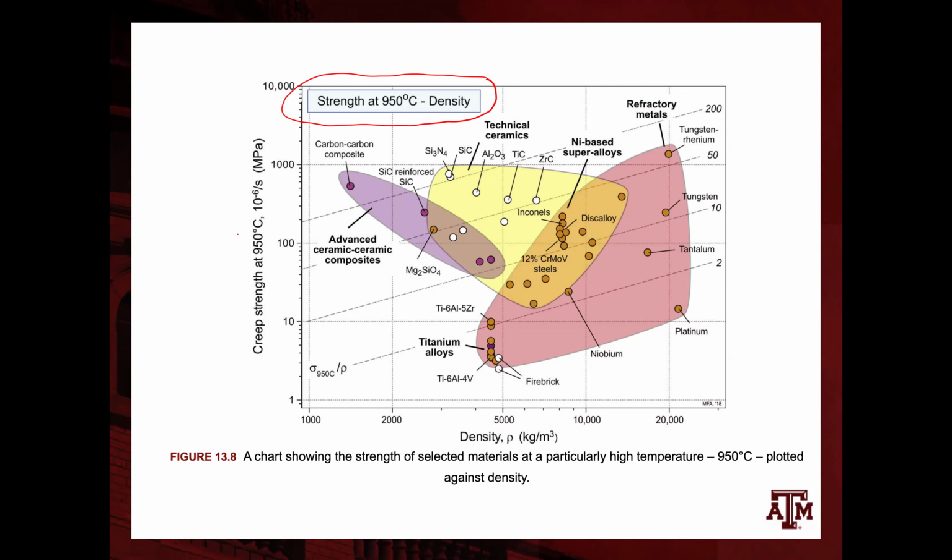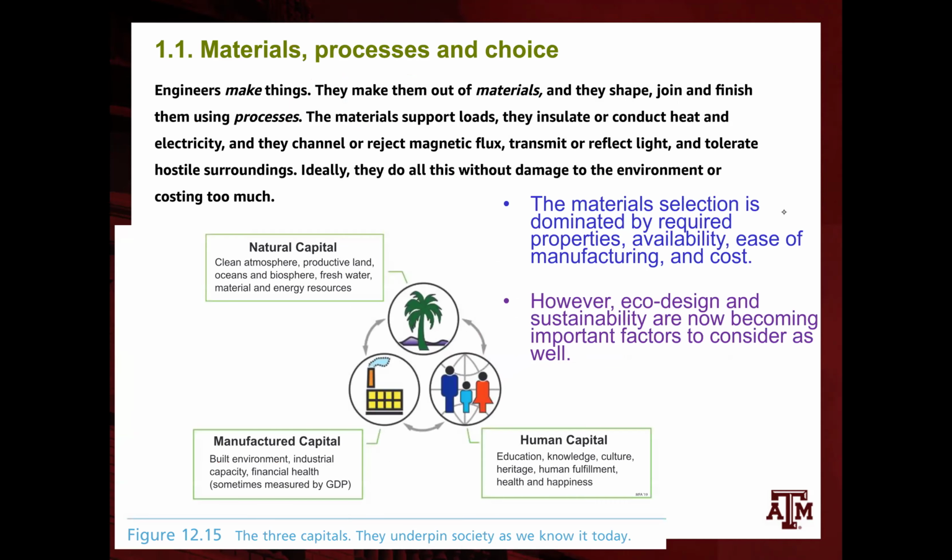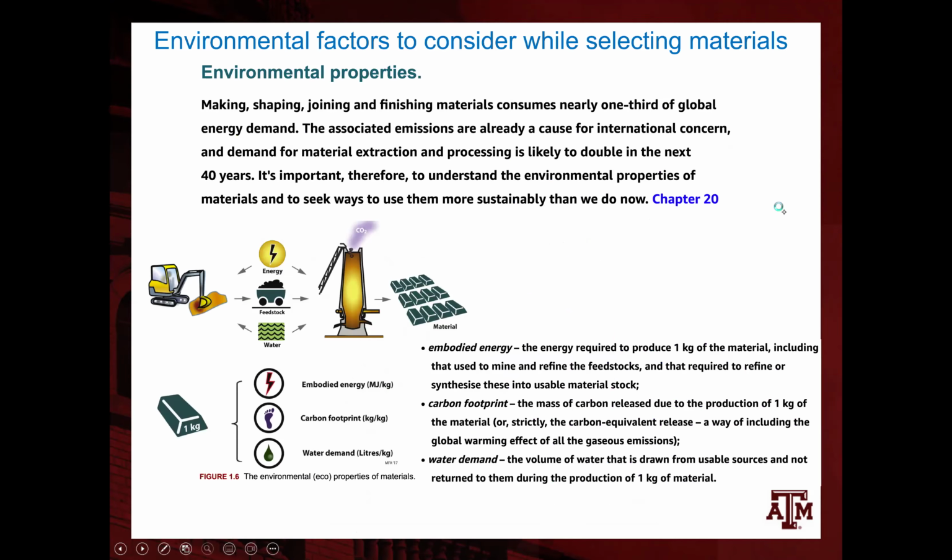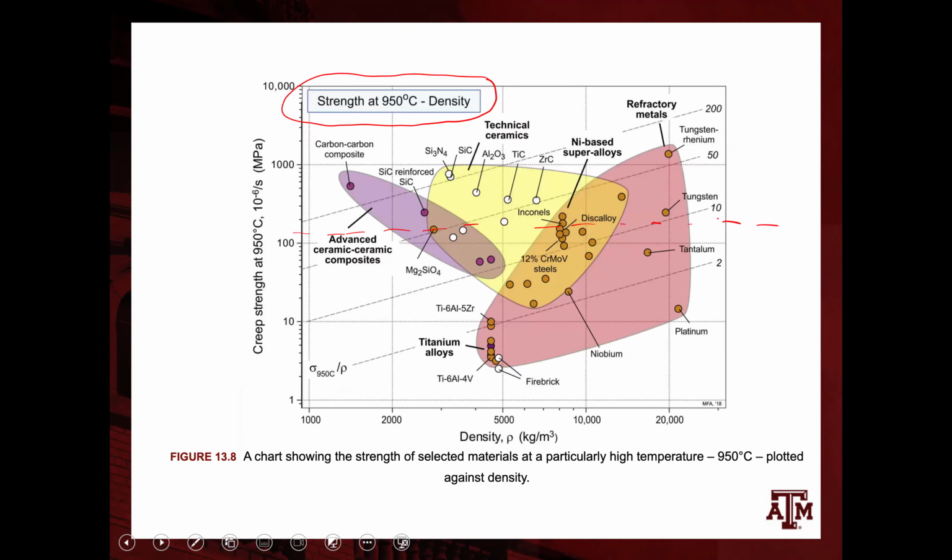If we try to find an option where the strength is above 100 megapascal, which in many applications would be really the bare minimum, anything above this line is our only option for materials with relatively high creep strength at relatively high temperature.